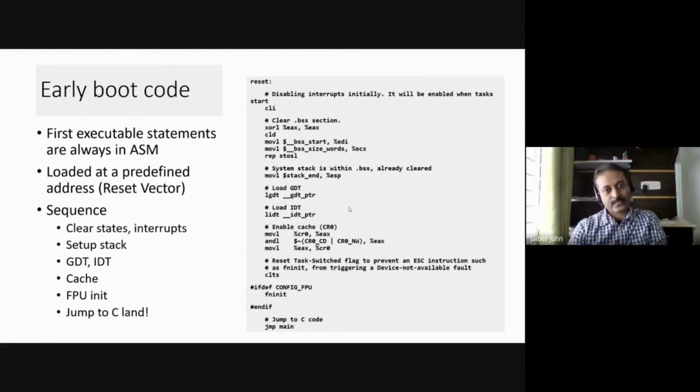But writing assembly means you'll be writing tons and tons of it, which can be easily simplified using high level. So only those critical things like early startup code, scheduling code, processor state changing code, system level calls, those critical sections where you can't write with high level, that's where people use assembly language.